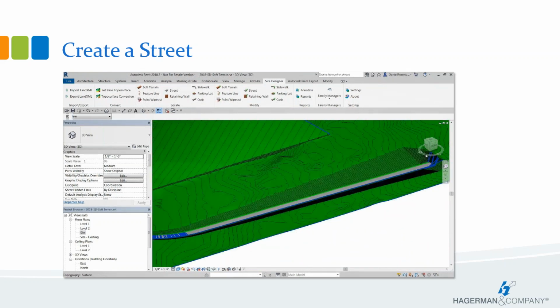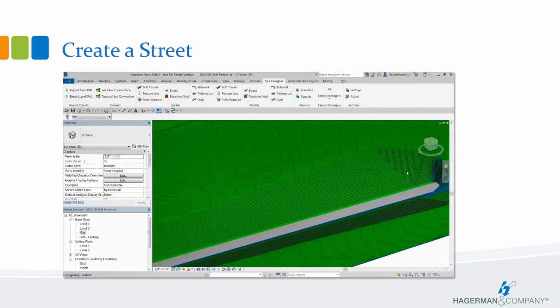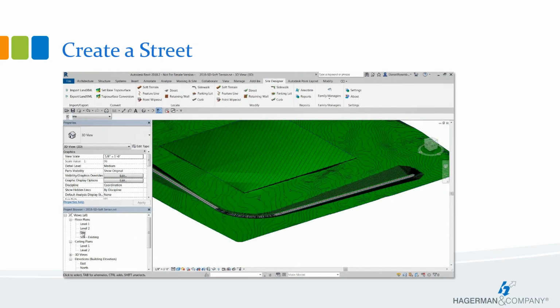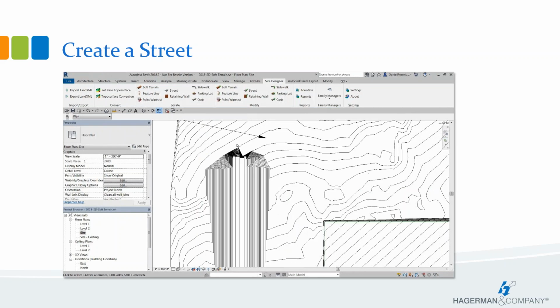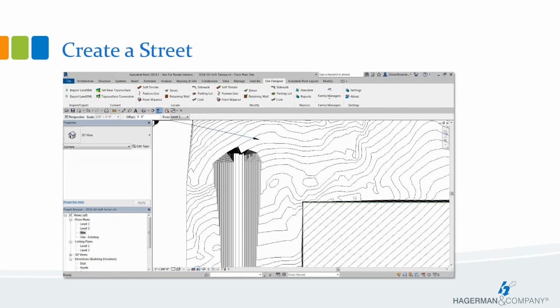And then let's kind of rotate around, check out where it cut. And then this is also one of my favorite things to do in Revit. You can drop a camera at the required elevation. In this case, I'm going to put it at 265.5 before placing it.